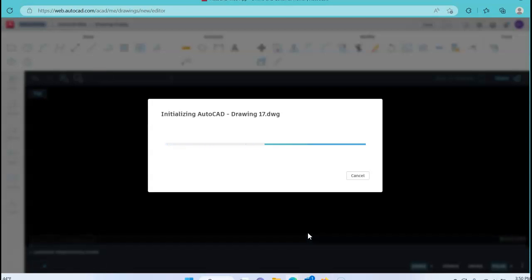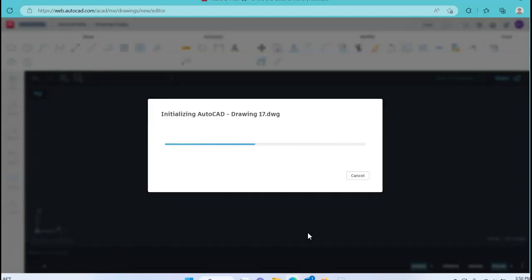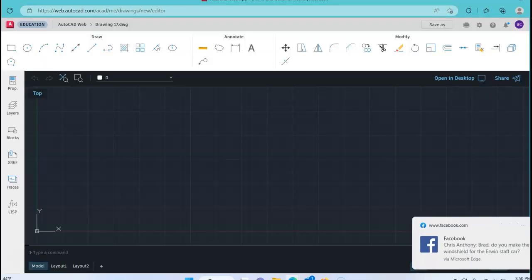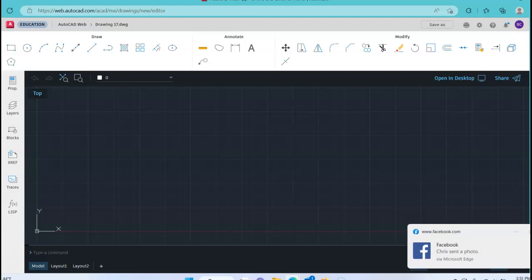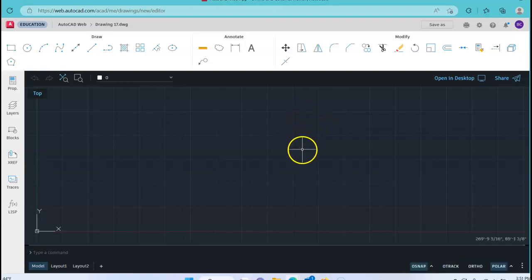And taking a look at that drawing, you see we've got 1, 2, 3, 4, 5 exterior lines on the part, and then we have 2 circles on the inside of this. And we are given some angles, so we know what some angles are, and some angles we don't know what they are. So we're going to take a look at this as we do that, and we're going to use coordinates and place our x0, y0 in the lower right hand corner.